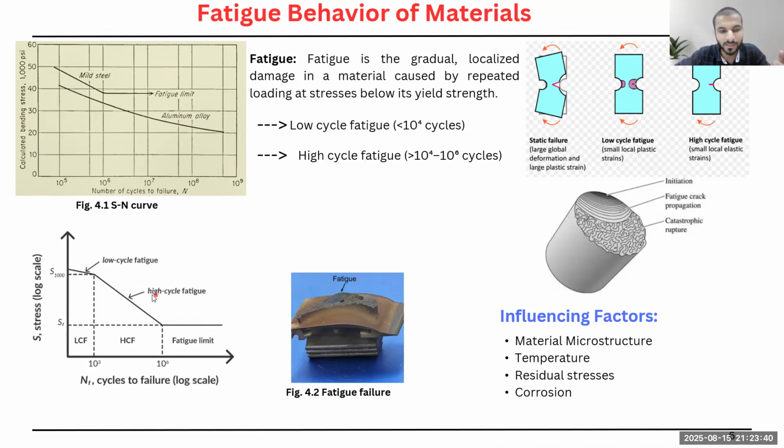And what this curve tells: you can observe here at low cycle fatigue, the value of stress is very high as compared to high cycle fatigue, due to which the initiation of a crack will lead to catastrophic failure. And these are the several factors which affect this fatigue behavior.